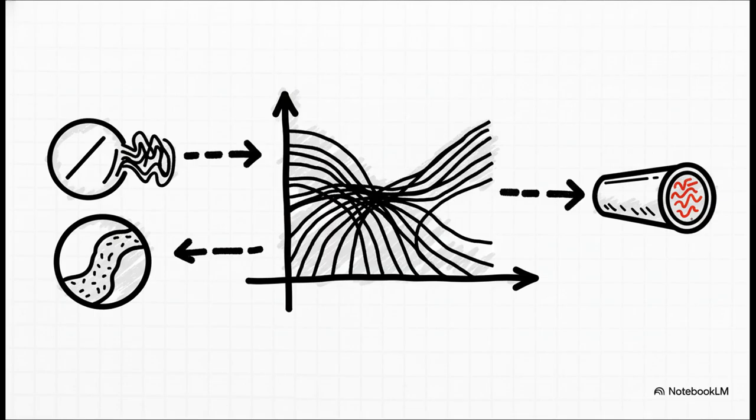We use a legendary tool that every engineer knows and loves, the Moody diagram. This thing is a masterpiece. It connects three crucial pieces of the puzzle: the Reynolds number, which tells us if the flow is calm or chaotic, the relative roughness, which is just how bumpy the inside of the pipe is, and the friction factor, which is our key to calculating the energy loss.